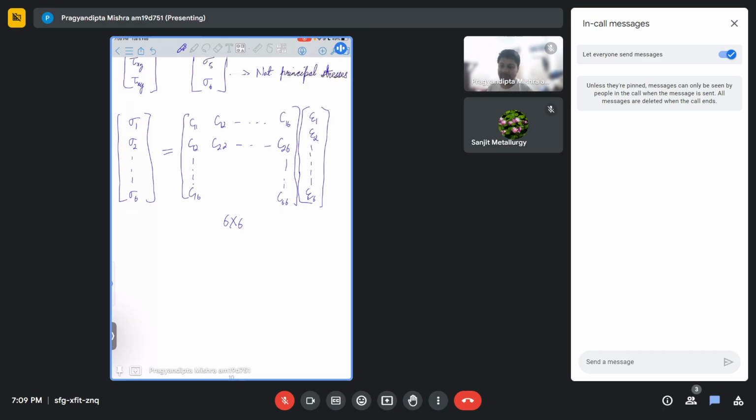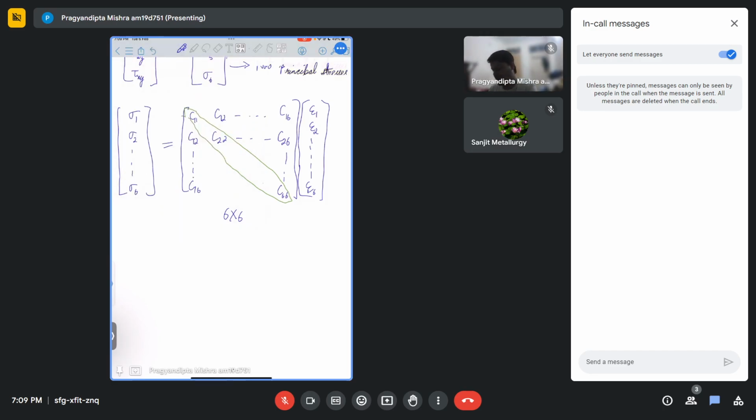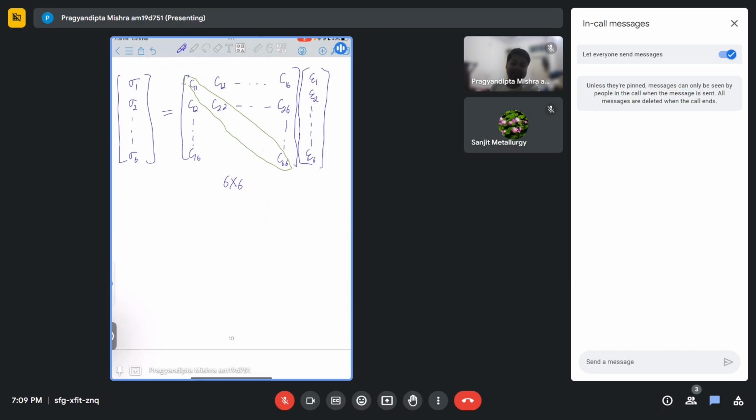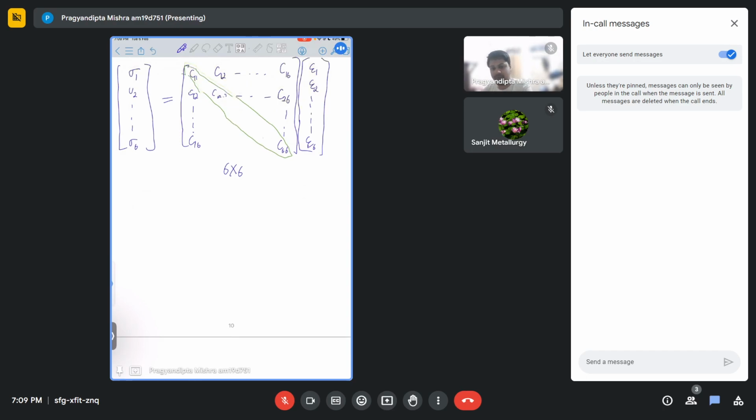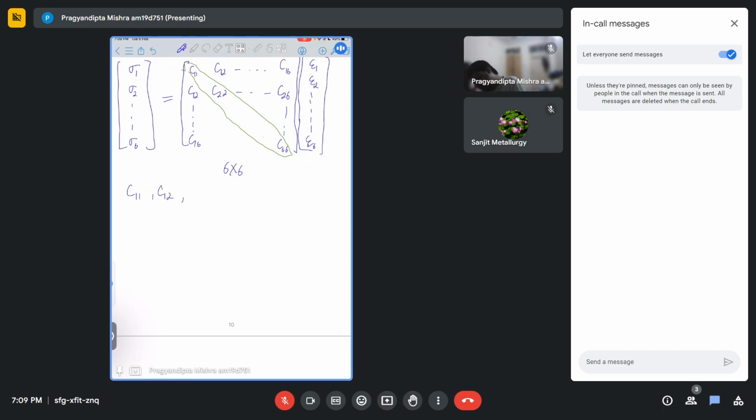One last thing that you can remember is these values of C11, C12, C13. Again, because stress and strain are symmetric, you will have symmetry here also. So essentially the elements above the diagonal and below the diagonal will be equal. Based on the specific material system we are looking at, your values will be either 0 or not 0. For instance, an isotropic material has only two constants, C11 and C12. So you will essentially have C11, C12, and then C44.